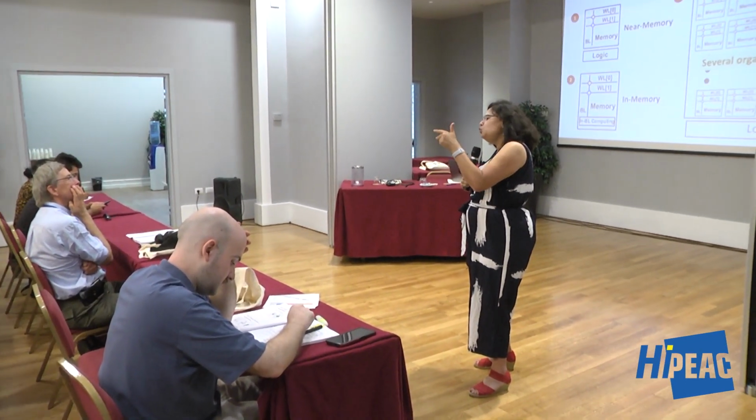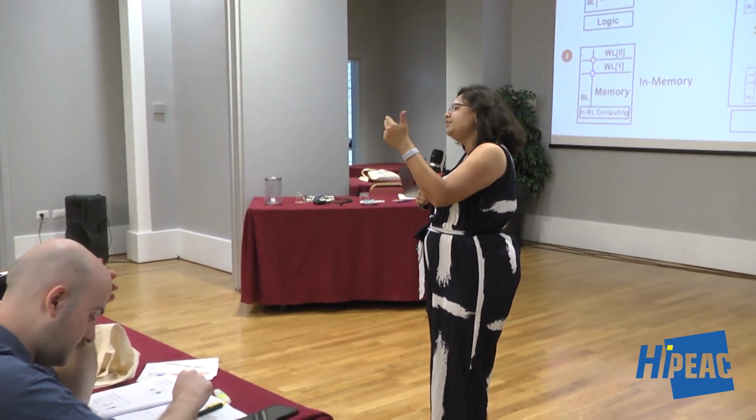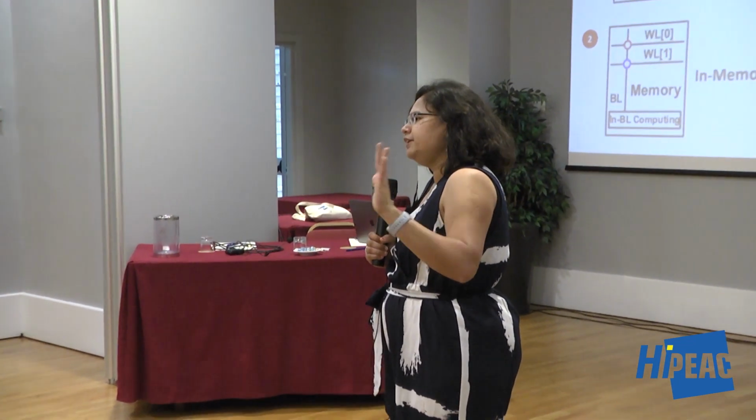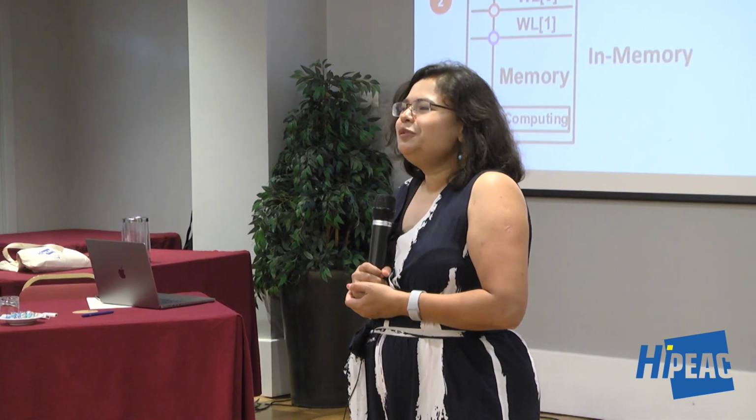But if you're doing 2 rows, I think you don't need to change anything, right? Like the conventional pre-charging sense amps would work. Yeah. Yes, absolutely. Because the wire resistance also starts adding in, right? So that can cause, yeah, there's a lot of issues there too. So it's a huge challenge for the circuit folks, I think, to make all this work.